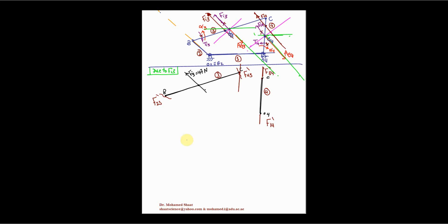How? Apply the procedure that we explained before in the previous video. We're going to start from a zero point. This is going to be the O_F, the zero point of the force polygon. Then initially you just draw the first fully defined force, which is this force of 47 Newton. So I can assume a scale of 1 to 1. To draw this one, I'm just going to draw a line that is completely parallel to this force in this direction.